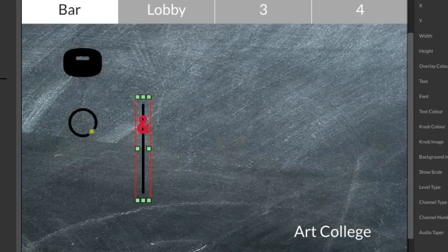In the on position, the fader will behave essentially like the fader on a mixing console, which is a non-linear scale called, in fact, audio taper. If I switch this option off, though, I can now specify a range of gain, maximum and minimum gain, that I want the user to have control of. Again, in installs, that's very useful because I might want to limit the maximum gain to 0 dB unity gain,